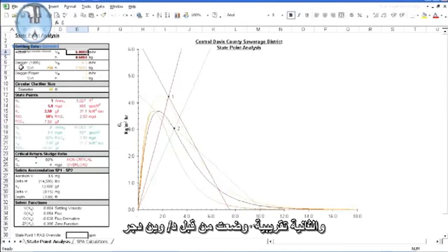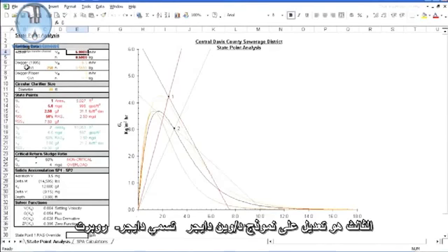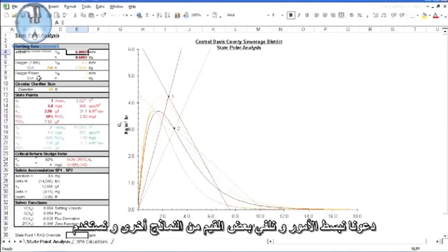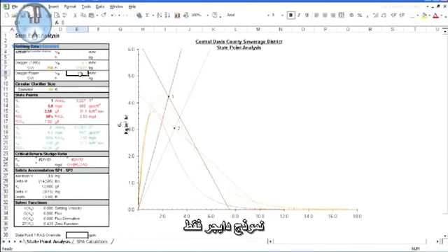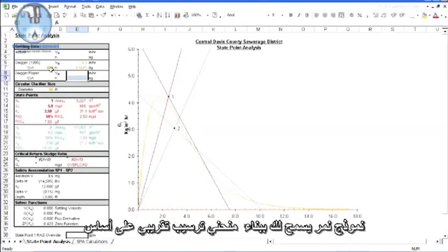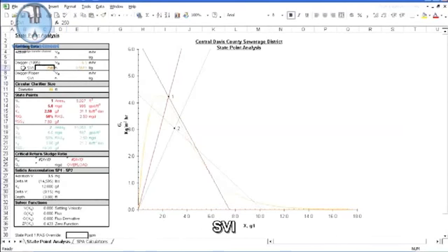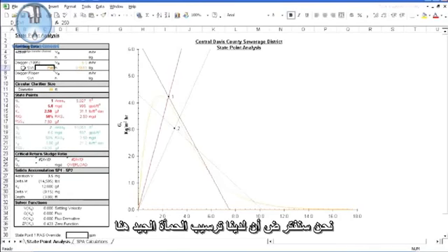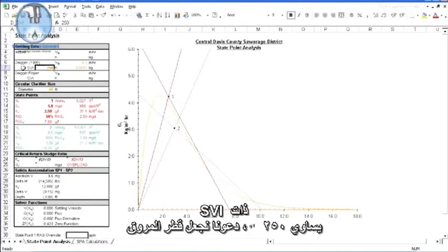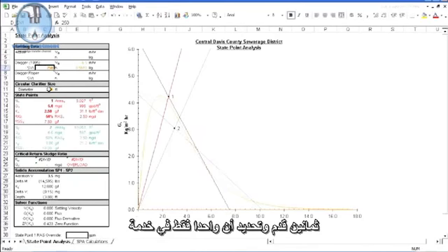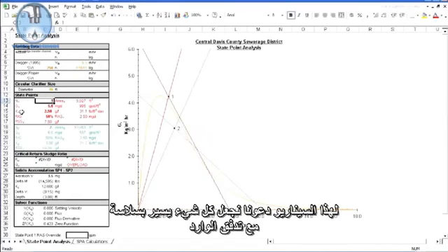The second is an approximation developed by Dr. Glenn Daiger. The third is a modification on the Daiger model called the Daiger-Roper. Let's simplify things and clear some values out of the other models and use just the Daiger model only. The Daiger model allows you to construct an approximate settling curve based on the SVI. We're going to assume that we have some decent settling sludge here, coming in with an SVI of 250. Let's make the clarifier diameter 80 feet and specify that only one is in service.